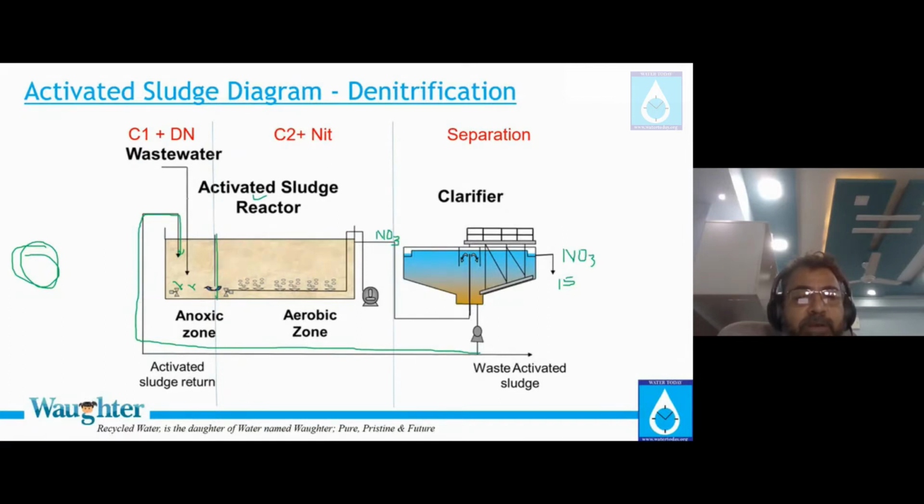Now the fresh water is coming into the anoxic zone. So whatever RBCOD is coming in this particular area will first be ingested by bacteria called heterotrophs. During that process, heterotrophs will bring this 15 ppm of nitrate coming into the system to 0 at this point. Therefore, this step is known as denitrification. It's written here: the first step is carbon level 1 removal and denitrification.